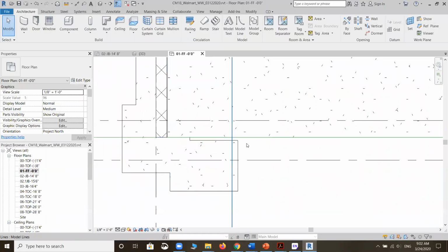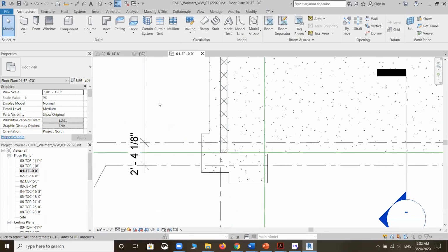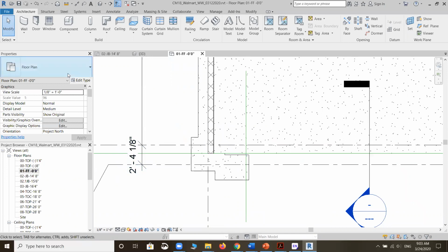Another thing we need to change actually is when you actually draw the first section of the curtain wall system, we are going to draw from 0 to 9 feet 8 inches. However, because we do not have a 9 feet 8 inch level line, you do not have a floor that is called 9 feet 8 inches. So technically speaking, you do not have a top constraint defined so far. So we need to actually define our own top constraints. Nevertheless, let's get started first.